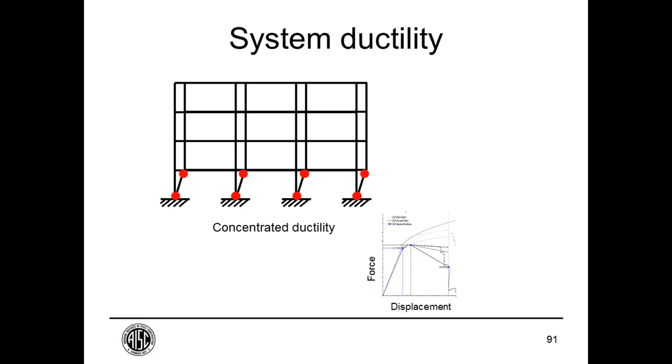And of course, if you have a 4, 6, 10-story building, and all the beams have the same strength, the demands on the beams lower in the building will be much larger than upper levels. And so that does tend to produce a very poorly proportioned structure that is highly likely to have damage concentrated in the first couple of stories and to have no inelastic demands in the upper stories of the building.